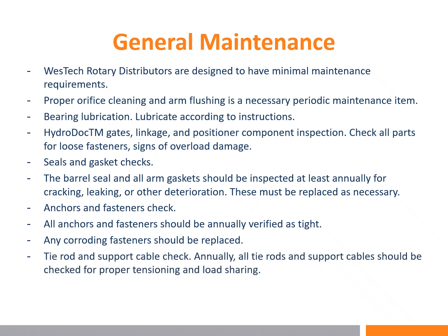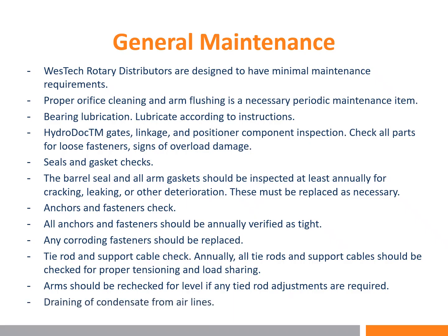Tie rod and support cable check. Annually, all tie rods and support cables should be checked for proper tensioning and load sharing. Arms should be rechecked for level if any tie rod adjustments are required. Draining of condensate from air lines.